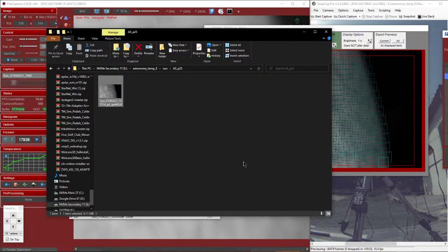Yeah, no, it's not USB-C, it's actually USB-B. It's type B. That's what connects to the cameras. But it's because it's USB 3.0 or 3.1, which has a very high bit rate. And the maximum you can get with a USB 3 cable without power, without being an active USB cable, is about 5 meters. After that, you will have disconnections.